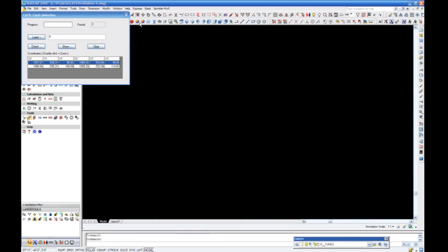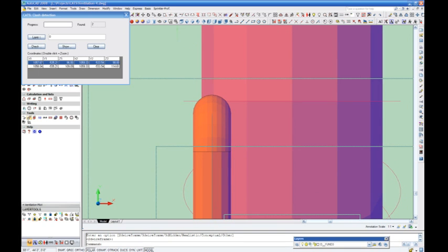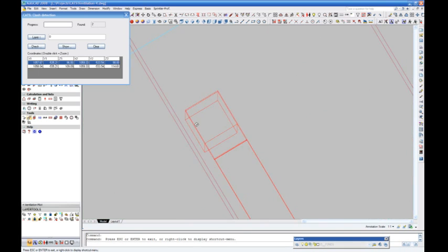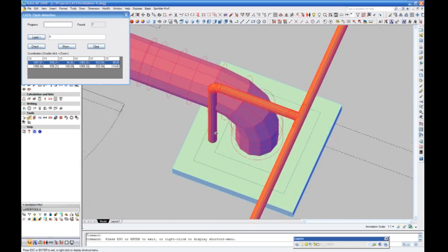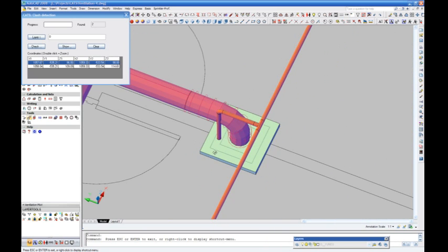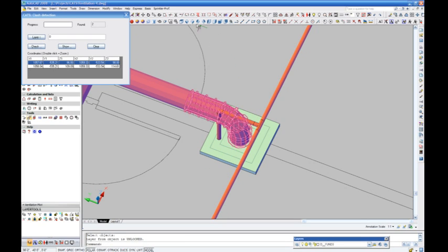Upon examination, we find the conflict between the flex duct and the sprinkler pipe, and the air diffuser and the sprinkler pipe. Obviously, the flex could be redirected. Inasmuch as the line also conflicts with the diffuser, we will relocate the diffuser to fix both collisions. We will now relocate and reconnect the diffuser.